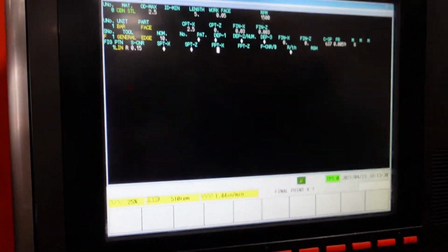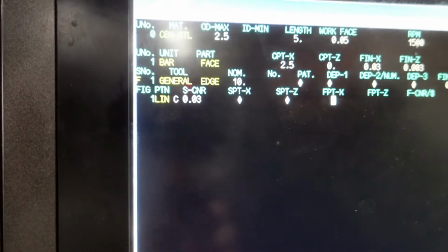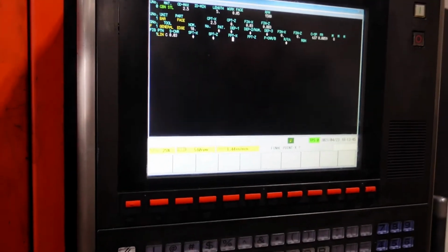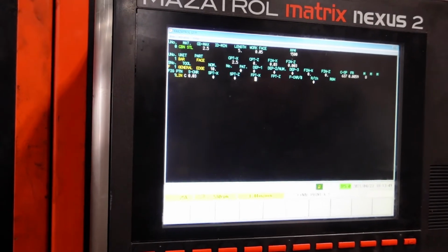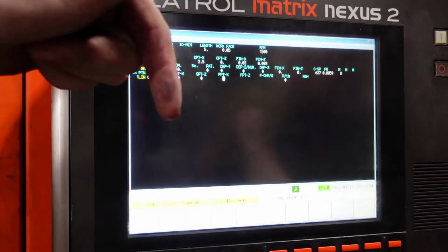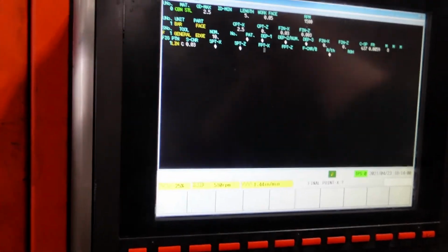So that'll be a general toolpath. But if I want to make it a corner, I just arrow back over here. I'll put in 0.03. That is a 30 thou, 45-degree corner break. It will always be 45 degrees unless your tooling is not described properly. And that 30 thou is measured in linear Z, linear X. Yep. It is not 30 thou across the length of the angle.